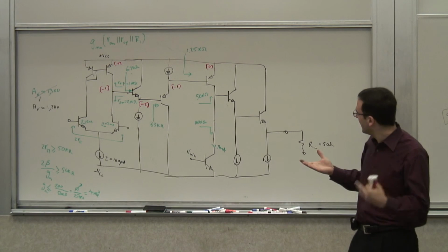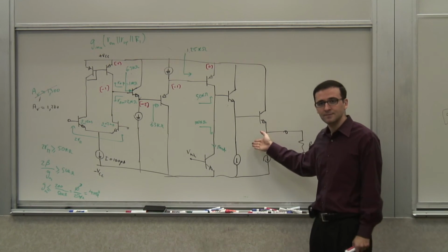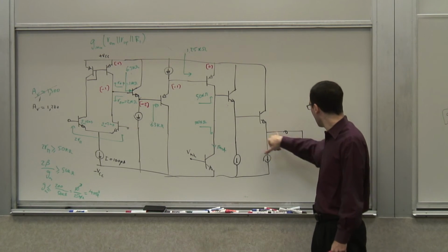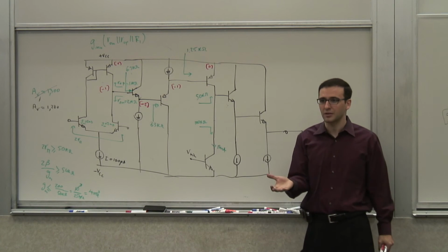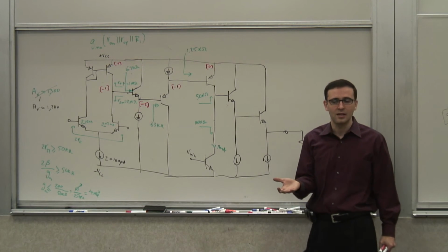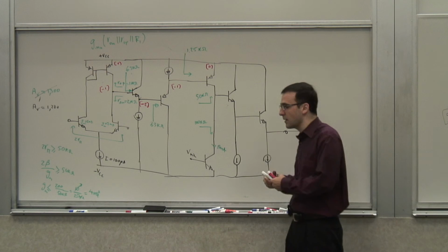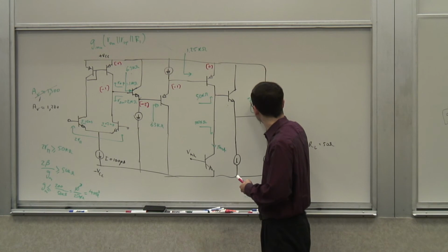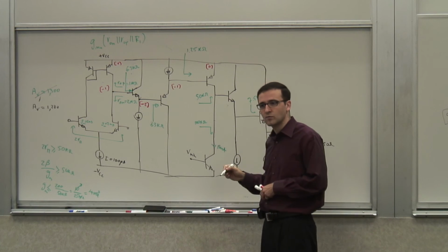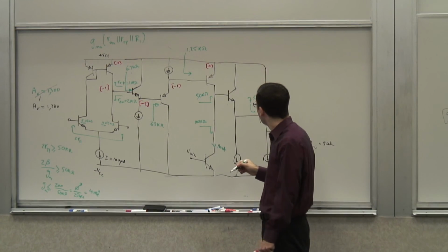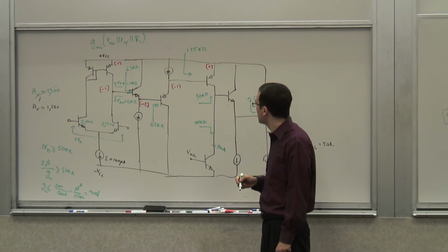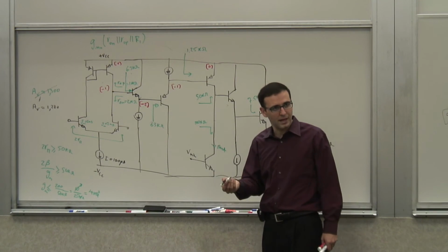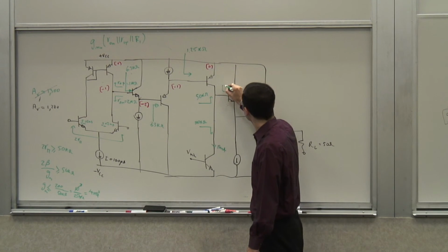But now, if it is running at, let's say, a milliamp again, now this is 25 ohms, this is 50 ohms, so I have to take that into account. I can't just drop it. So 75 ohms multiplied by beta 100, so that's 7.5 kilo ohms approximately, right? And now that goes up there to what value? Multiplied by another beta, so that gives me 750.